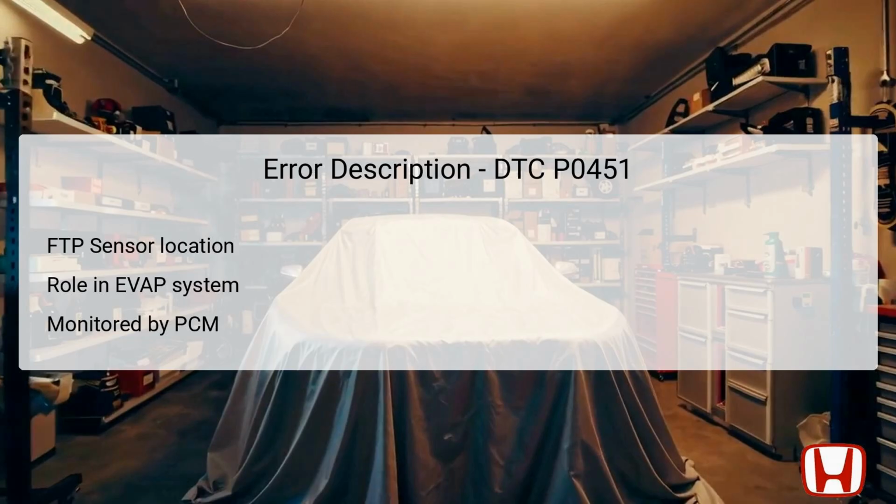The fuel tank pressure (FTP) sensor, located on the evaporative emission (EVAP) canister, is a vital component for detecting leaks within the system. Responsible for providing real-time fuel tank pressure data, the sensor allows the Powertrain Control Module (PCM) to efficiently monitor and manage the vehicle's emissions.